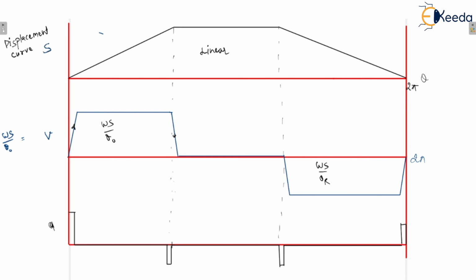Again in this condition you can see that the velocity decreases during the return stroke for a short period of time, so again there will be a retardation, but as the cycle is completed, it will increase up to 0, so there will be an acceleration. One more important thing: this is the diagram of acceleration. You can match this to this condition, like that.